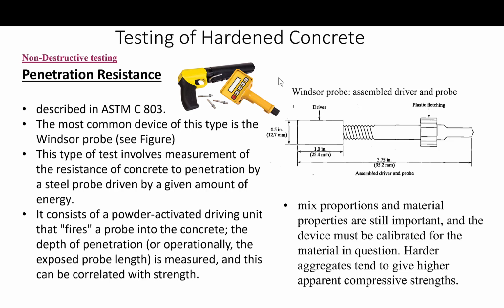But all this will not be a substitute for eventually doing, for example, drilled cores and testing them, or doing petrographic examination, or sometimes even chemical analysis, as we've done. But if you become familiar with them and know how to interpret their results, they're excellent starting tools to steer you in the right direction. I'm not warning you not to use them, but when you use them, make sure you know how to use them. That's all I'm saying.